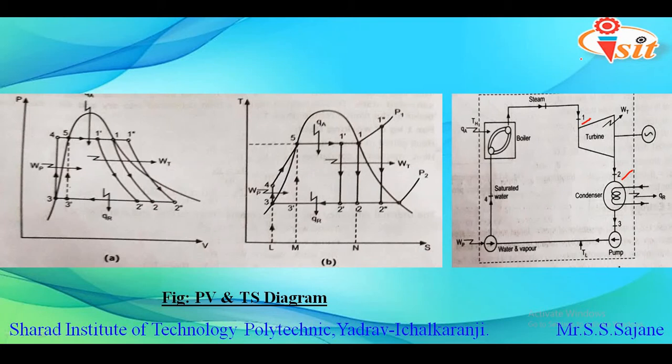Now the second process, that is process 2 to 3. If we refer to the diagram of the steam power plant, between these numbers 2 to 3 we have the element called the condenser. In the PV and TS diagram, the line represented by 2 to 3 is called a constant pressure process.